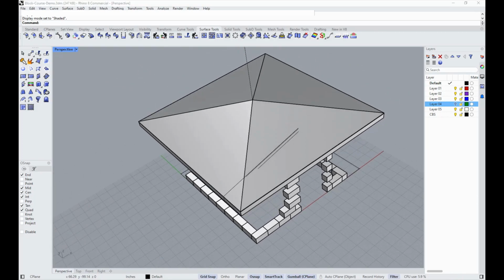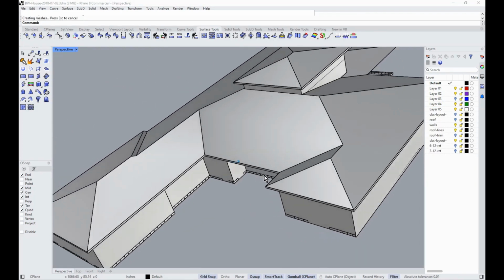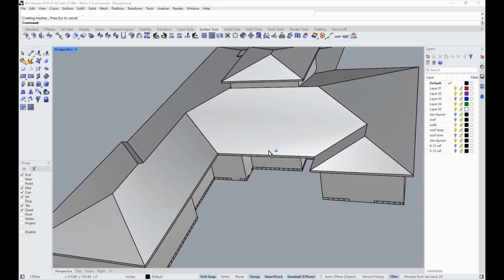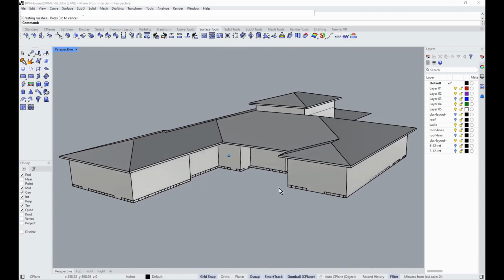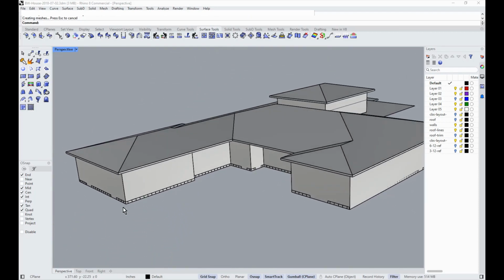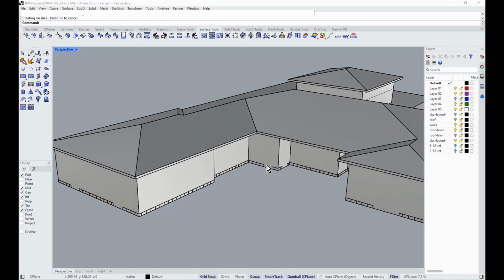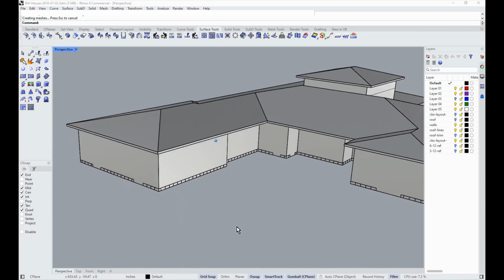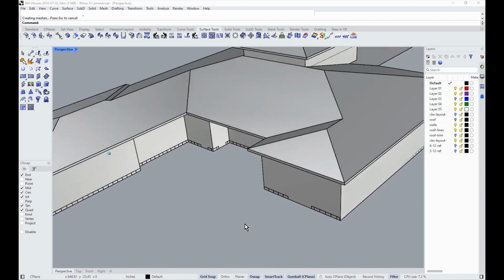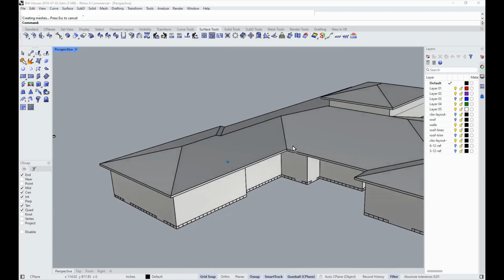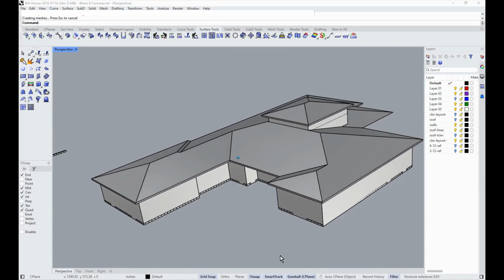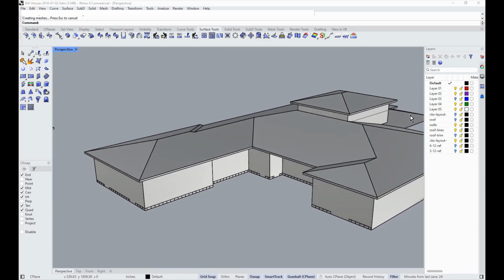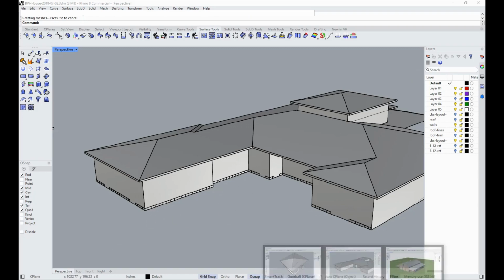Going over that, let's see here, jumping back to this one, you got valleys, which would be basically the same thing running in reverse. And even on this one, you can see how we did block course just to set a true wall length on the 8-inch cinder block grid. We have things like doors or windows wherever we wanted to break for whatever reason, and built from there. So you're getting a true structure. And you can see we're not running the cinder blocks all three-dimensionally. It's just to help with the plan form.